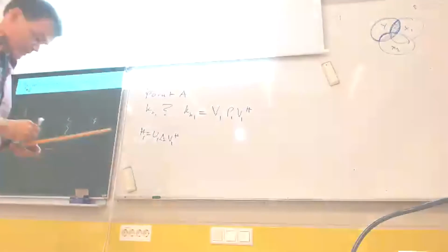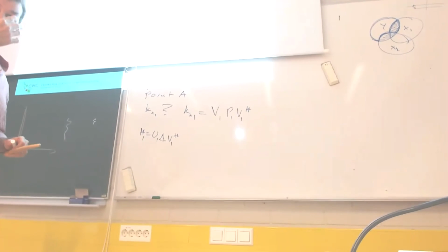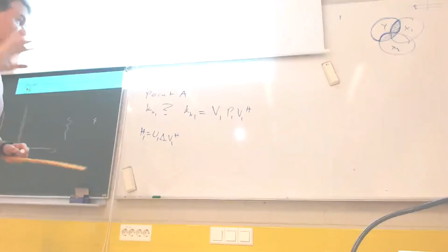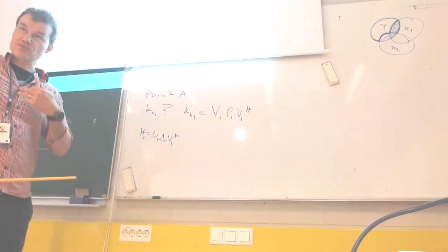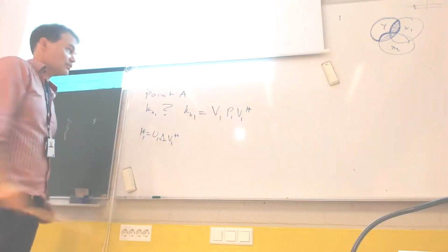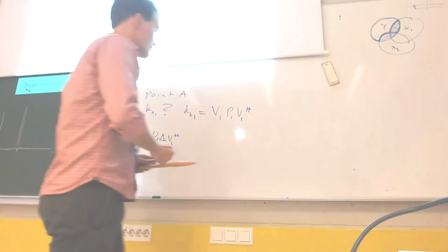This would be the transmit covariance matrix. User 1 is decoded last without any interference. So also the transmit strategy can be designed assuming no interference, and that's the point to point MIMO. This would be the maximum rate.